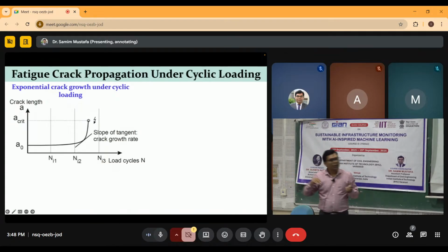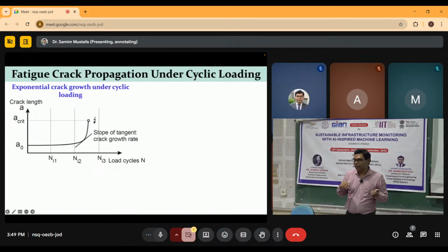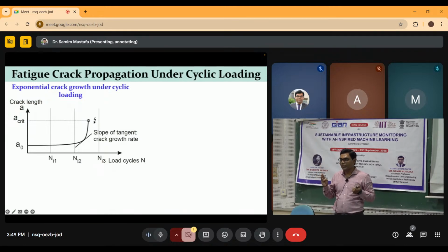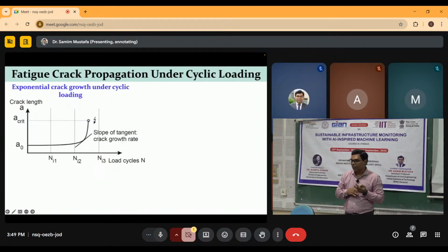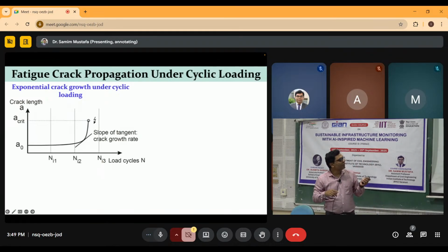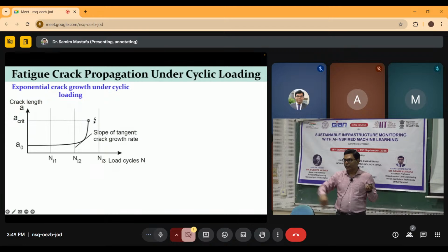increase, okay. So fatigue crack is also very difficult to predict and also very difficult to measure, means how much fatigue growth has taken place, unless you measure the vehicle loading, then only you have a better understanding that it is subject to this much of stress cycle. So there is a relationship between the fatigue crack growth and the number of stress cycles, okay, there is an equation. So for example, this is happening exponentially, and before going into the next inspection you will realize that there is a subsequent fatigue growth.